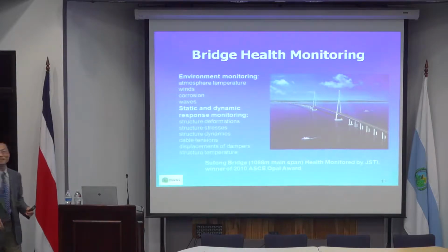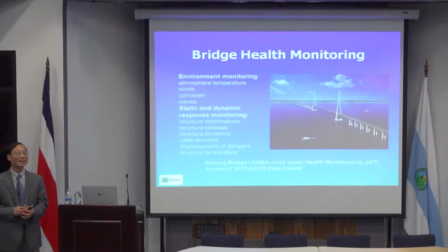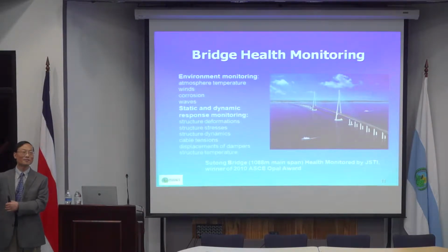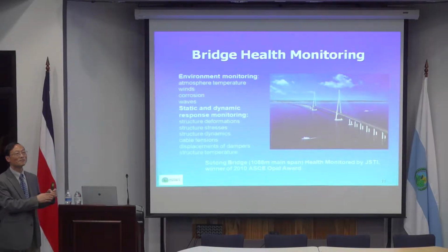So, the questions for load testing. The concept is very, very simple. Just do a test to get accurate data on deflection, stress, strain, and sometimes you can also detect vibration frequencies, and then you use a finite element model to best fit all these outcomes of the data you tested.